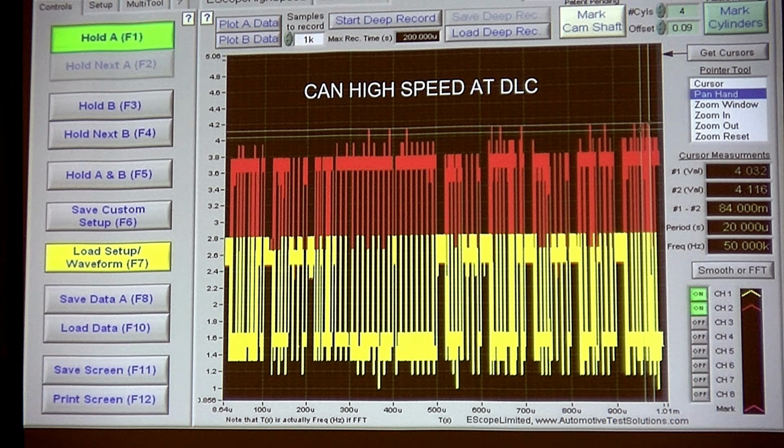If you want to decode it, don't you have another five modules on there that have been programmed to decode these messages? Don't they understand it better than we can? Use them. They're going to help you fix the car because they're coded in the same coding as what's happening on the bus to fail. If I can look at all the data and see what other modules are telling me has failed, I'm going to do way better than trying to get a scope and do this. But I've got to know that the basic voltage lines are okay.